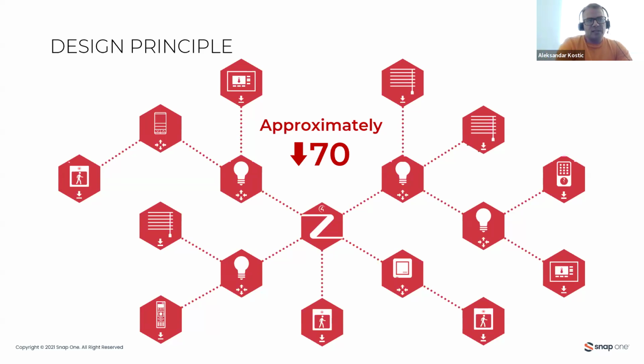So the worst case would be to use a Control4 controller as an access point from the basement or from a rack or from any other closed metal environment, because it kills the Zigbee signal completely. So just have in mind that placement of the Control4 controller acting as Zigbee access point is crucial to good Zigbee communication.